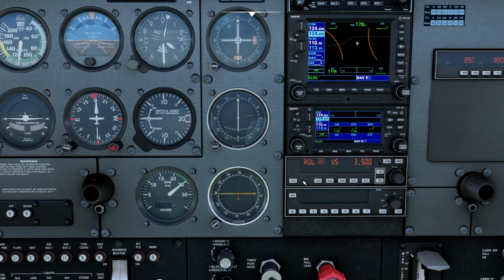The default vertical mode, once you turn the autopilot on, is a vertical speed hold mode of 0 feet per minute. And you can see when we first turn on the autopilot, it shows VS in the pitch mode indicator window, and then it shows 0 feet per minute initially in the altitude pre-select and vertical speed indication window. And so it's just going to hold us at a vertical speed of 0.